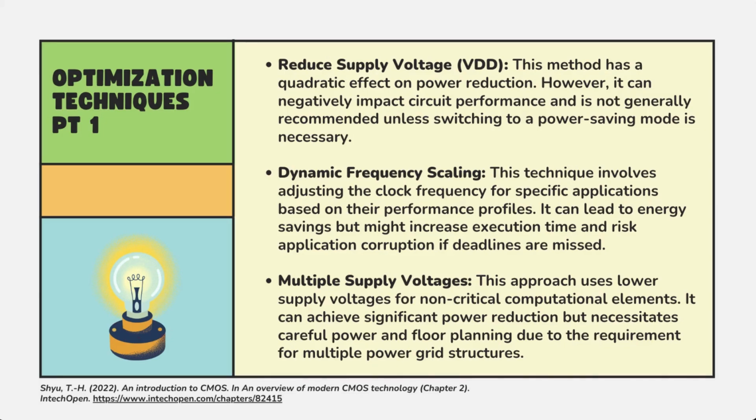Third one is multiple supply voltage. This approach uses lower supply voltage on non-critical computational elements. It can achieve significant power reduction but necessitates careful power and floor planning due to the requirement of multiple power grid structures.